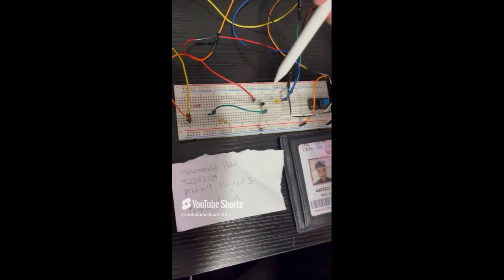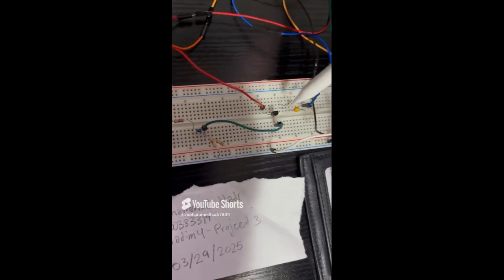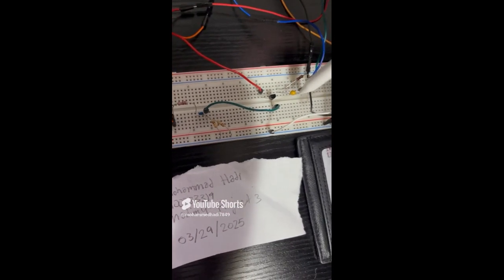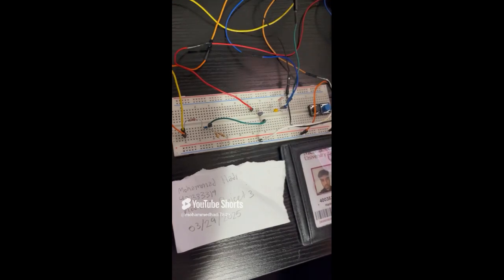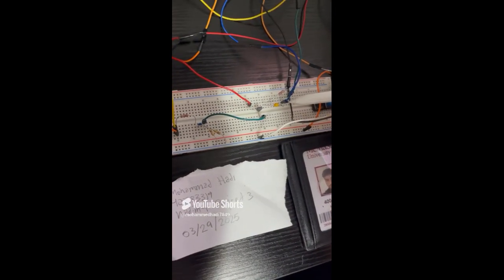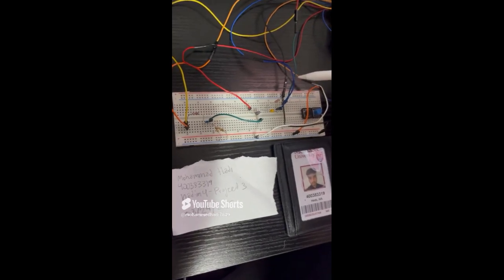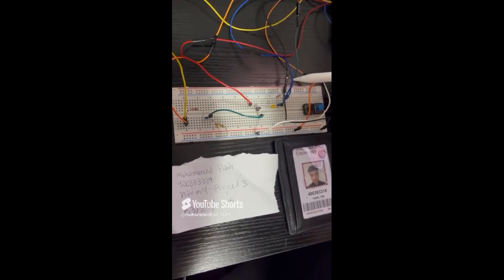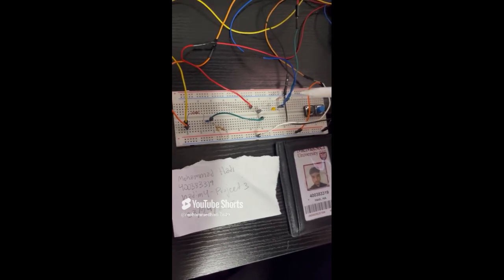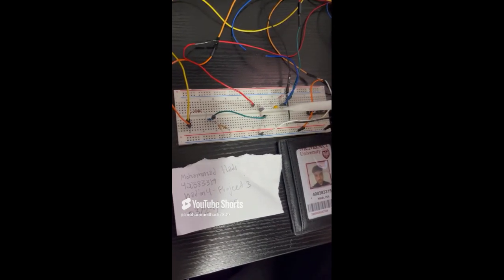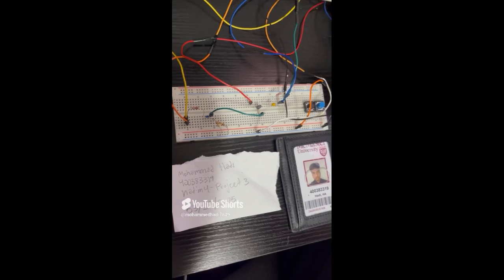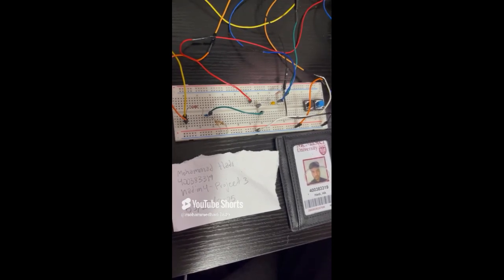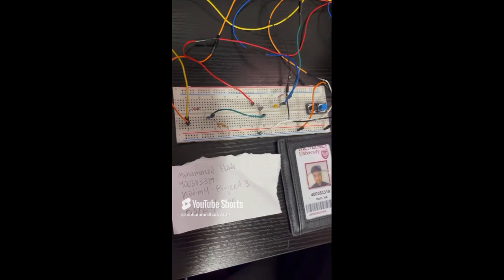Moving on, now we're at the emitter side, which, as you can see, is connected to the same node as the 100 nanofarad capacitor and the 100 ohm resistor. They both go to separate nodes. The capacitor, this blue wire, is equal to positive channel 2, and that is what the other side of the capacitor is equal to. The 100 ohm resistor is in the same node as this green wire, which is basically a -5 voltage from the 82.